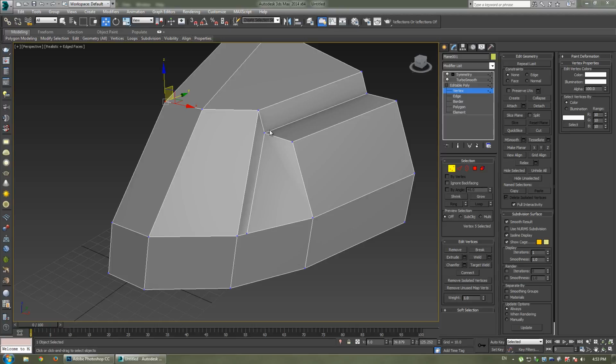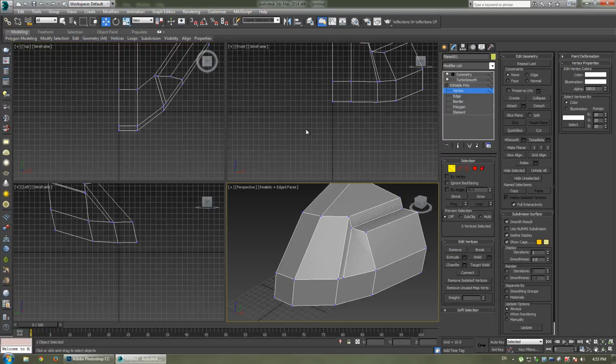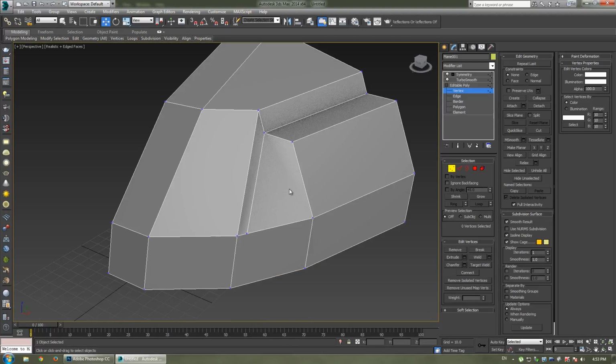I use my pinky for control, and I use my thumb for maximizing the viewport. So my fingers don't really move from that location. When I want to use the arc rotate mode, I move my finger off the W key onto the S key. So my middle finger goes from the W to the S.